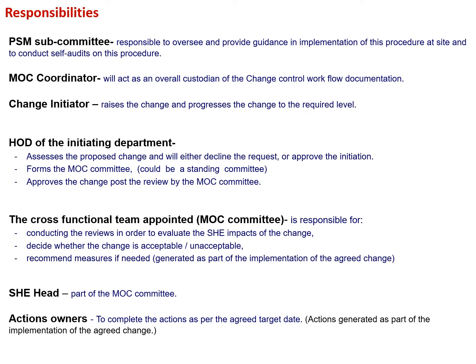So what are the responsibilities? What is the responsibility of the PSM subcommittee? The PSM subcommittee is responsible to oversee and provide guidance in implementation of this procedure at site and to conduct self audits on this procedure. MOC coordinator: he will act as an overall custodian of the change control workflow documentation. Change initiator: he raises the change and progresses the change to the required level.